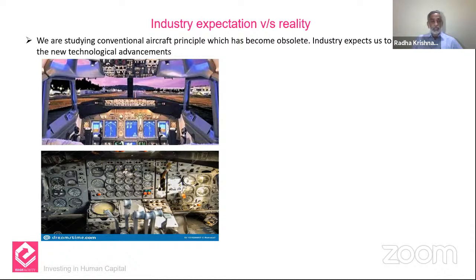The first technology was where sensors were directly giving the information to the indicator, whereas now the sensor information is digitized, controlled by engine control, and then presented to the pilot. On that particular indicator, he gets not only the information about the aircraft engines, but he also gets the information called the crew alert warning system. If there is something wrong, he will be alerted what exactly is the problem. And he is also instructed in that system, now you take this action to get over this problem.